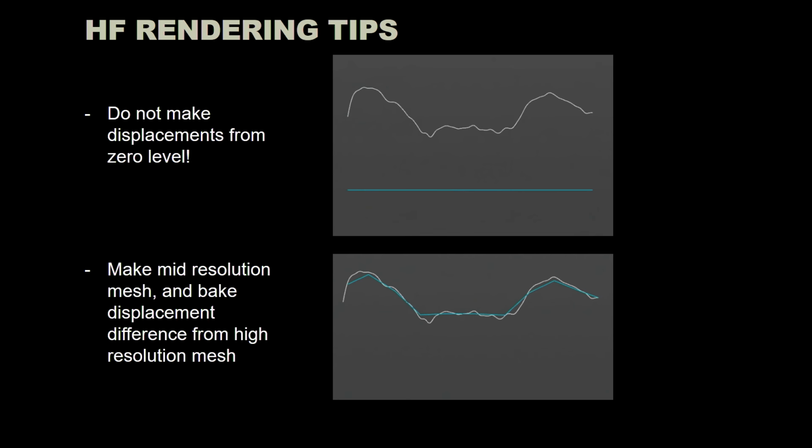Okay, so really important tip for rendering height fields in Karma. Never do displacements of height field from zero. This will eat all of your RAM.